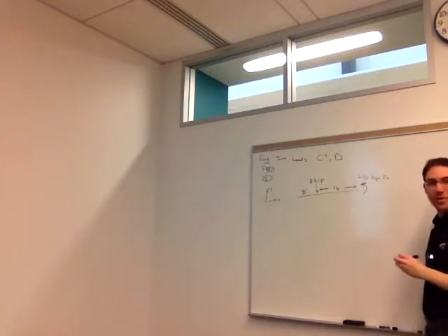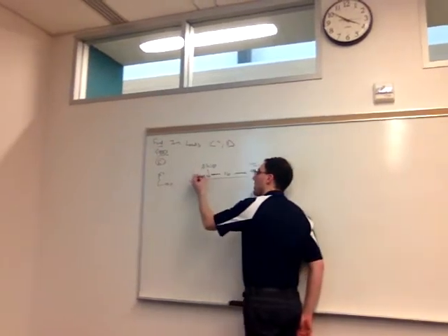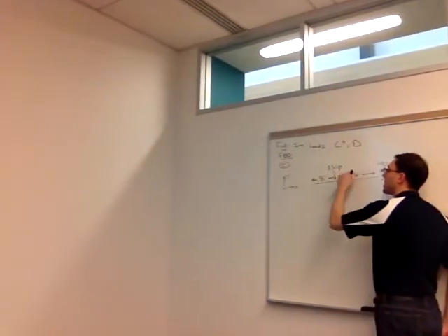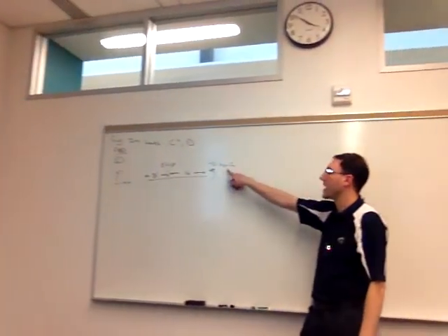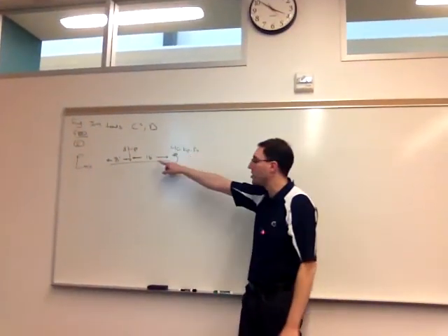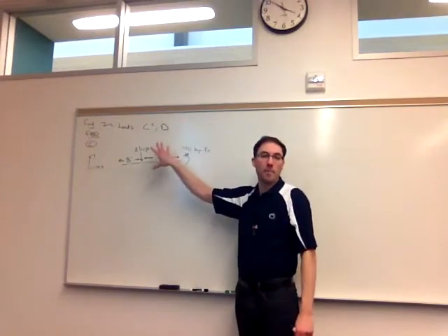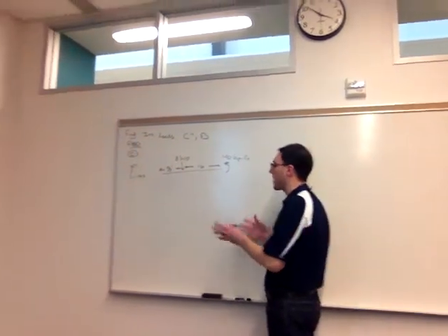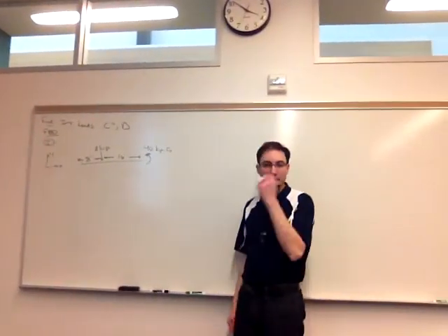We want to make sure that all of our units are consistent before we go too far forward. All of our lengths are in feet. Our one external load is in kip, and our couple is in kip feet. If there was a mixture of inches or pounds and kip or inches and feet, we would want to make everything in the same units so that when we go to the equation step, all of that will make sense together.